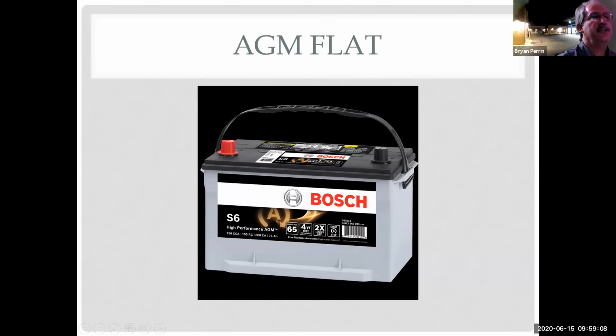So this is an AGM flat. This is what the original equipment manufacturers use. We also have special charging precautions for AGM batteries and special chargers for AGM batteries. I can't use a regular battery charger on them.